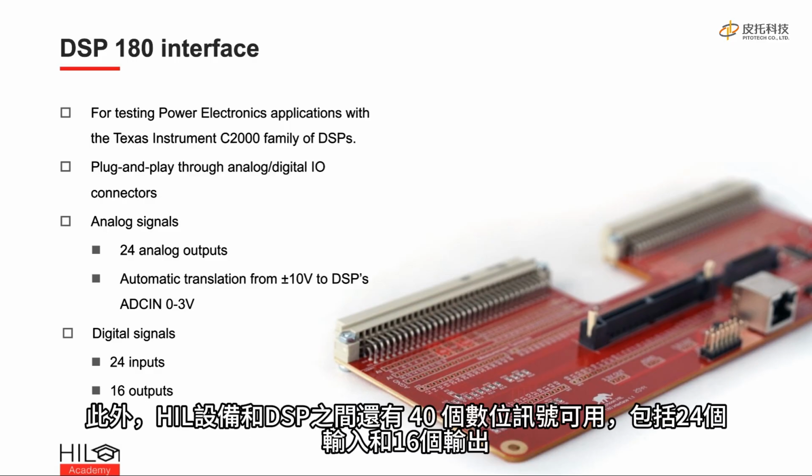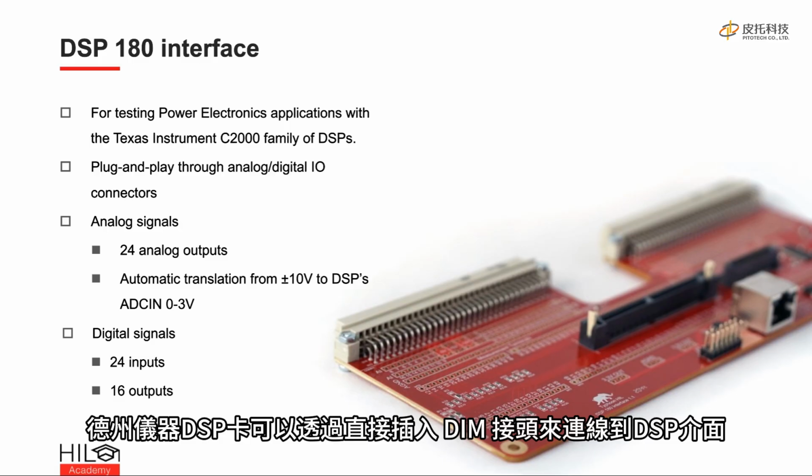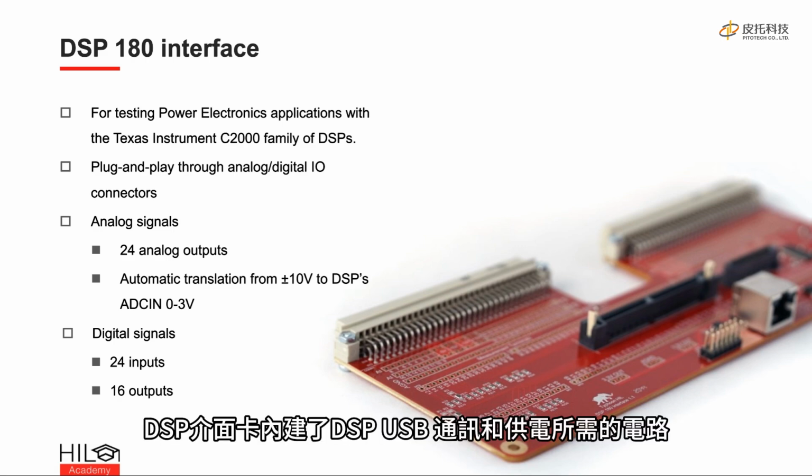In addition, there are 40 digital signals, 24 inputs and 16 outputs, available between the HIL device and the DSP. Texas Instruments DSP cards can be connected to the DSP interface by plugging them in directly to the DIMM connector. The DSP interface card has the built-in circuitry required for the USB communication and power supply for the DSP.